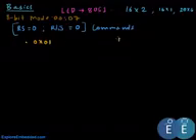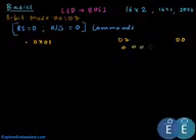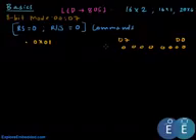So if D7 is here and this is D0, if all the bits are 0 and only the D0 bit is 1, it clears the display. So this is in hex, so it clears the display.